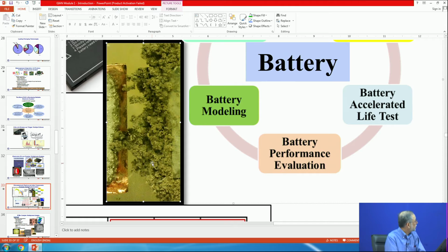Okay, so if moisture gets into your battery, eventually, this is of course an extreme case because we ran some highly accelerated tests in the lab. So in reality, you won't see such dramatic amounts of dendritic growth, but you'll see smaller dendrites that have grown from one cathode to anode through the separator sheet in between, and eventually those cause electrical shorts, and that causes a problem. So some of those fires that we were getting in lithium-ion batteries, Sony had the problem.